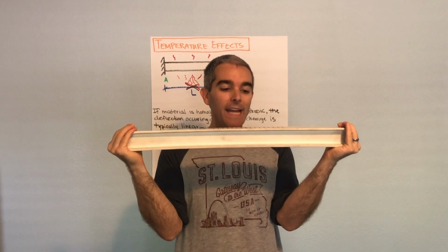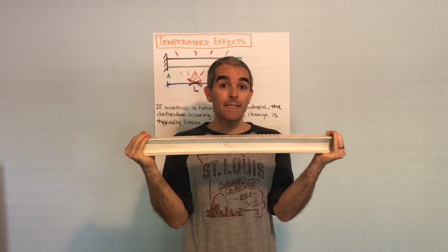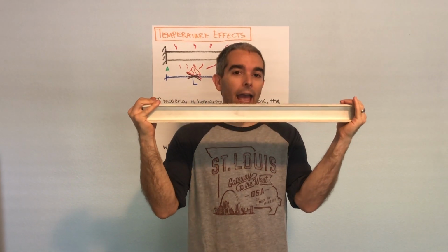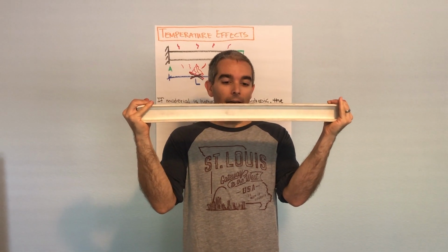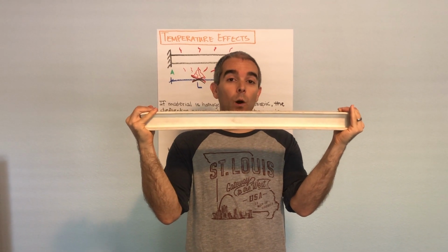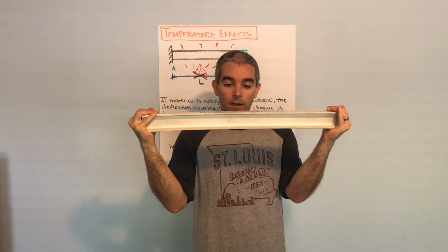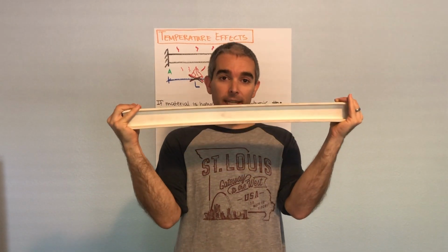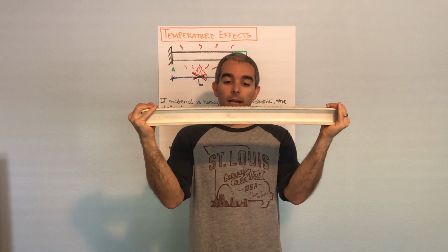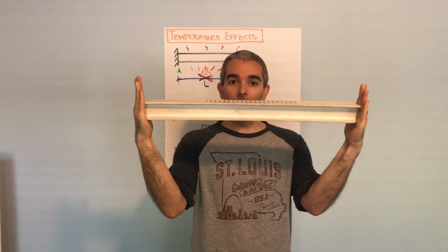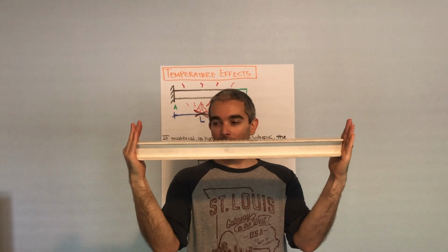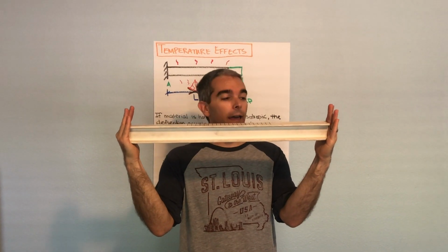I think you can imagine that the girder would expand, right? But if I have it fixed at both A and B, as the girder tries to expand, what will happen? Well, it's likely that the girder will develop compression, because I have fixed or very rigid walls, it can't expand anywhere. It's not free to expand on either end.